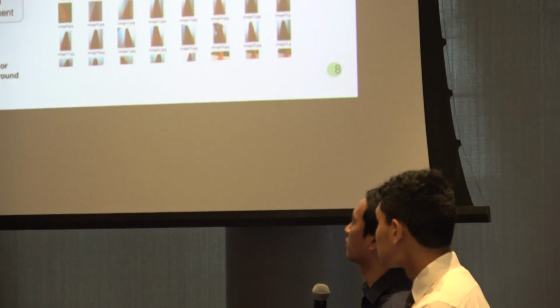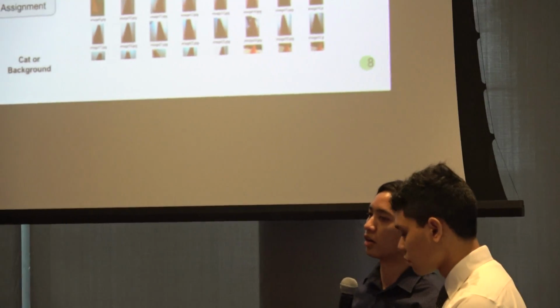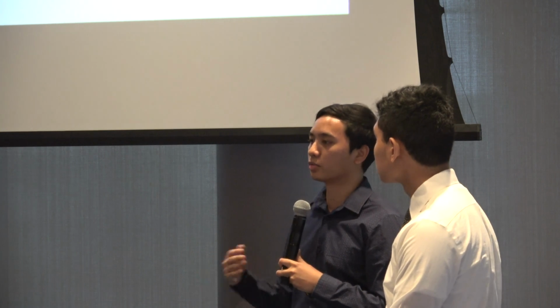As you can see, we used the Haar-like features option to extract the wavelets within the images of our cones and build a classifier out of that. And then after that, we had to implement it into our Python script, which determined whether there were obstacles on our path.